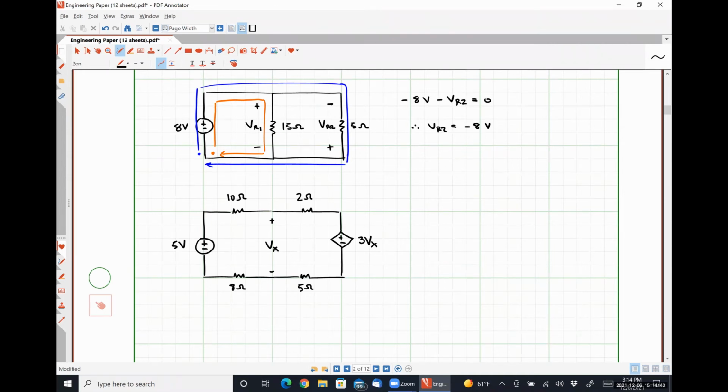Okay. So it stands to reason that if a current is flowing in this circuit, the same current flows through all of the elements. We'll prove that in about 5 minutes using Kirchhoff's current law, right? So what I'm saying is, let's say that I have some current I here. That same current I has to be flowing here, as well as here, as well as here, as well as here, right? So that's one current I just circulates around that single loop because we know no current can branch off and flow through that open circuit in the middle, because open circuit current has to be 0.